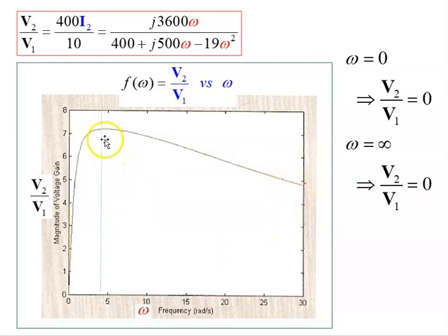If we want to find the maximum voltage gain with respect to omega, then we'd have to take the first derivative of this with respect to omega and solve for omega. We'll end up solving for omega being plus or minus j something. So omega will turn out to be an imaginary number, and we'll find out more about that in the next module where we'll analyze the S-plane.